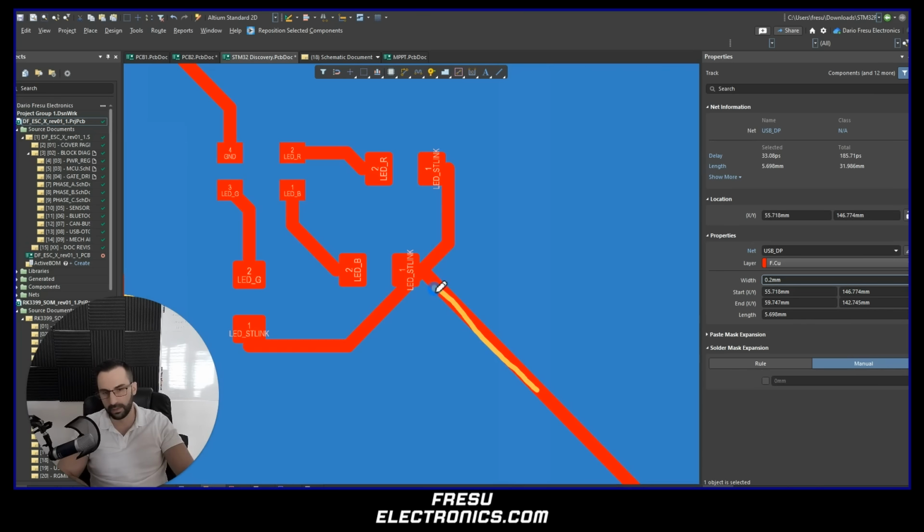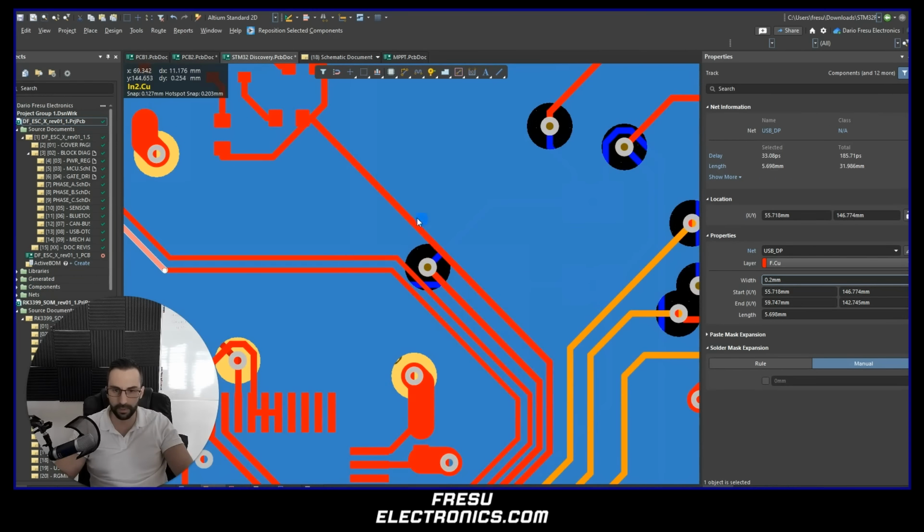And then here is where we create the reflection. The signal will come to this point, and then some part of it will reflect back, and some part of it will propagate to one side and the other part will propagate to the other side. But the signal that you are going to measure is going to be compromised, because now it is not the full signal anymore but a portion of the signal. And then you have to account for the reflection, because, like we said, one portion of the signal will reflect back, and you don't know what this reflection is going to cause. If it keeps propagating back, then it reaches this point, and in here there can be some crosstalk. So the signal spreads also into this trace, and it's just going to create a big mess in our circuit. And this can result in signal integrity and/or EMC issues.